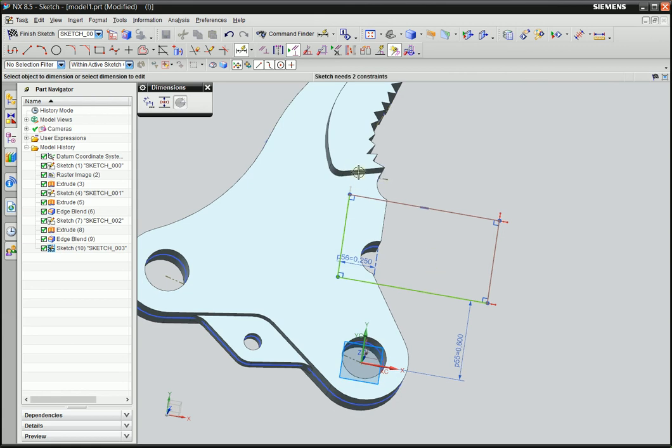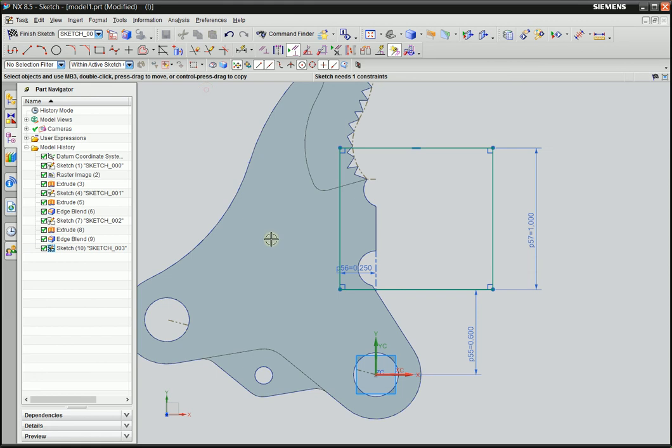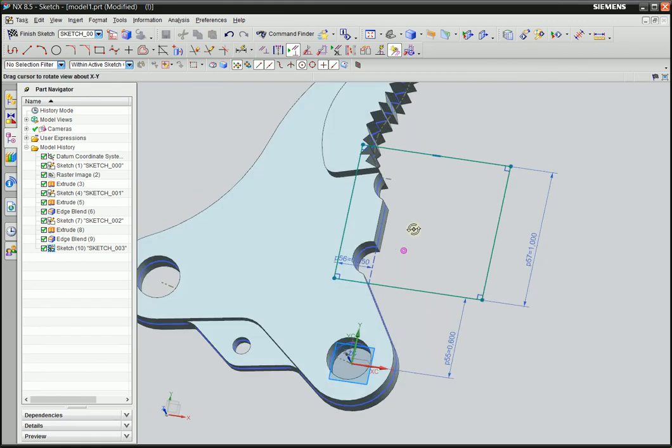And if you look at that, the blade is going to cut all the way in here except the teeth. That's why when I did the extrude on the teeth, I didn't unite them together, because now when you cut into this big piece, if you unite them, it's also going to cut into that teeth, which I don't want. So what we can do is put a dimension, maybe 1, make it bigger, because you're going to cut into that anyway. So I think we're good.